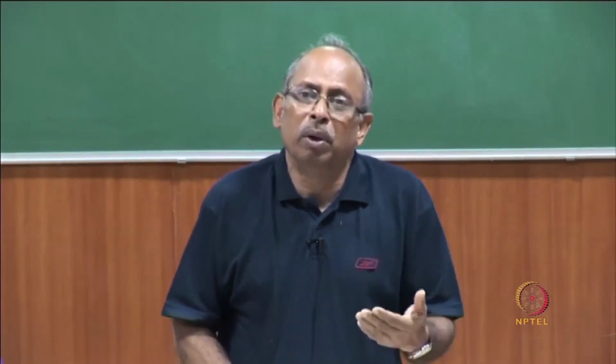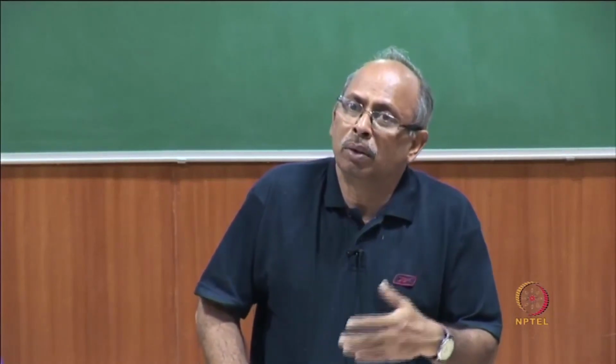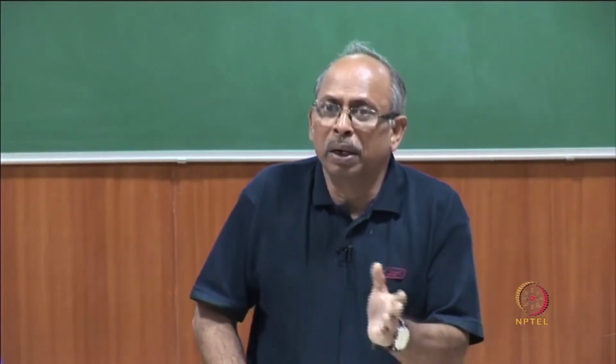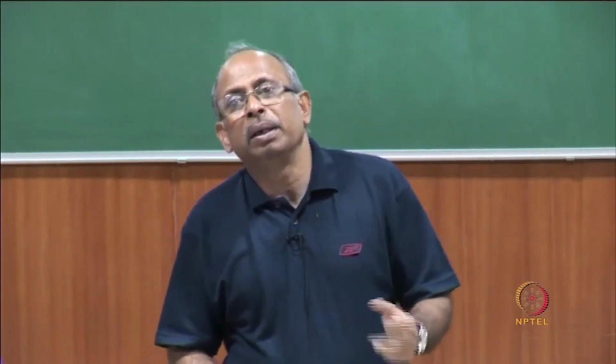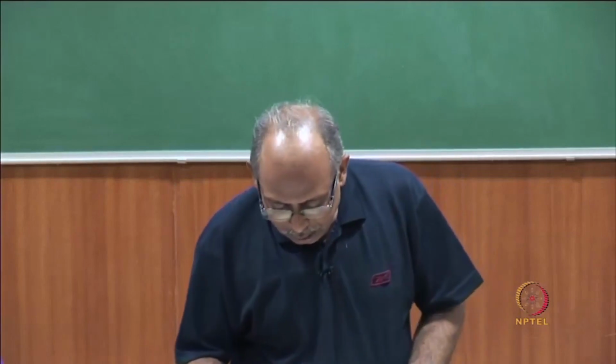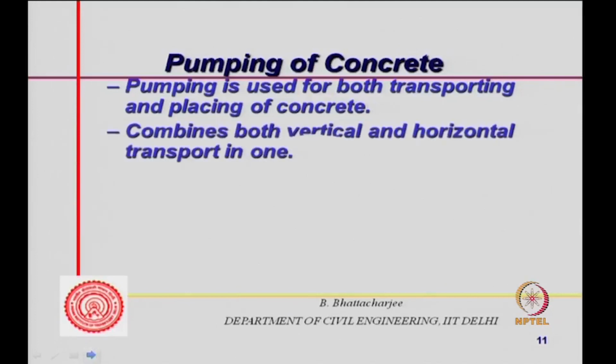So, therefore, pumpable concrete cannot be simply normal concrete proportioning. You might have to proportion it a little bit carefully, so that it remains pumpable, right. Okay. So, pumping is used both for transporting and placing of concrete. You can place it straight away onto the mold, and it combines both vertical and horizontal transport in one. Therefore, it is very versatile.